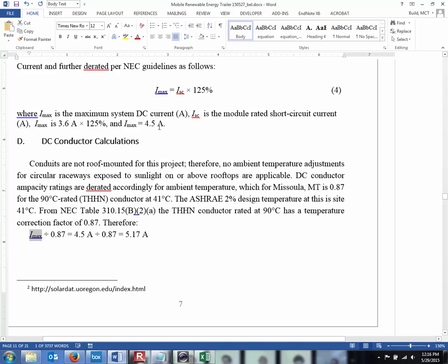Okay, let's think about this. I have to go back into my... Okay, so we'll want to read through this and see how the ampacity is affected. Because I think basically the way it works is the hotter that wire gets, the less current it can reliably hold. But the .87 is throwing me off a little bit.